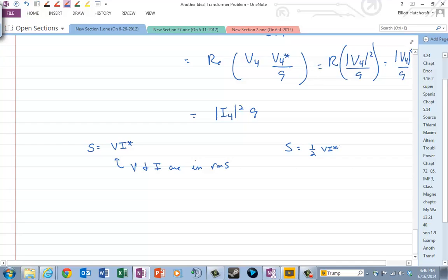You must bear that in mind, and notice it's because the power in each case turns out to be the same. You don't have different values for power, but you calculate power differently to get the same power values if you are in peak value or if you are in RMS value. And of course, as I said, to get a VRMS for a sinusoid, you take the peak value and you divide it by the square root of 2. Same for a current.